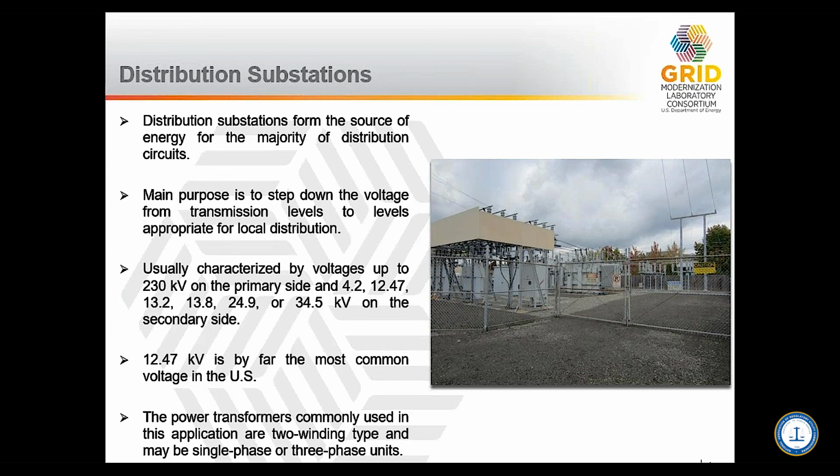And so when you look at distribution systems, their role is, how do I phrase this? There are multiple substations when you go between the source of generating power and consuming it. The reason goes back to what I said before: we typically generate power at a distant location and we want to get it to the house. For that to be efficient, we want to move it up to a very high voltage in the hundreds of thousands of volts, but we need to get it down to lower voltages in the house, or the building. And so the substations are where that occurs.